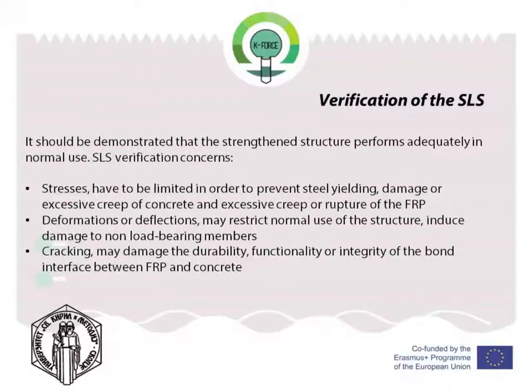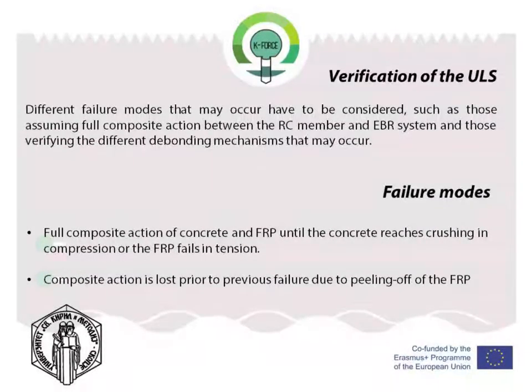Deformations, which may restrict normal use of the structure or induce damage to non-load-bearing members. Cracking, which may damage the durability and functionality of the structure, or which may endanger the integrity of the bond interface between FRP and concrete. For the ultimate limit state, different failure modes that may occur have to be considered.